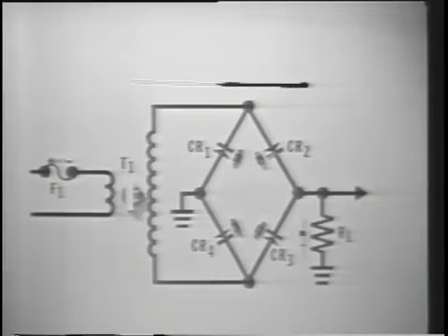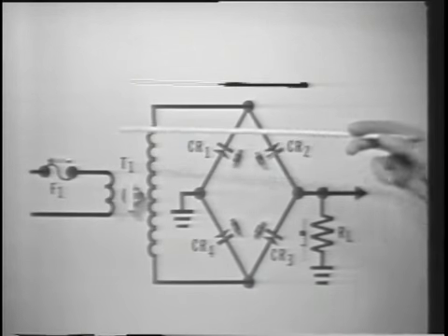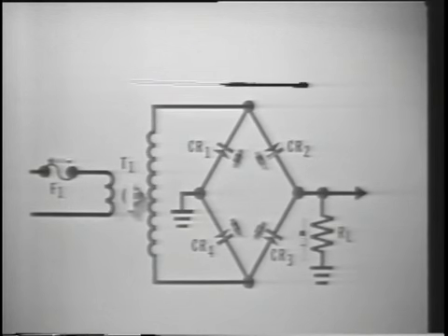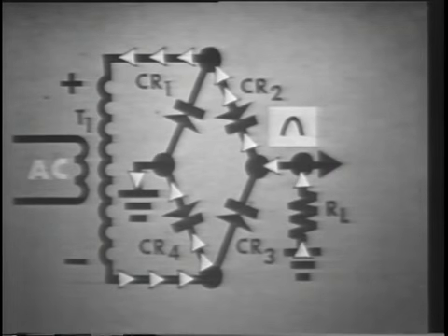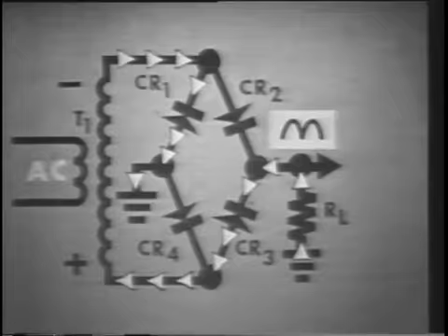Well, the first thing to check, of course, is the fuse. If it's blown, you will have no output. But let's assume for now that the fuse is good. So what else do we check? Remember, there are two distinct paths for current flow in this circuit. One path is used to produce one pulse in the output. The other path produces the other pulse.